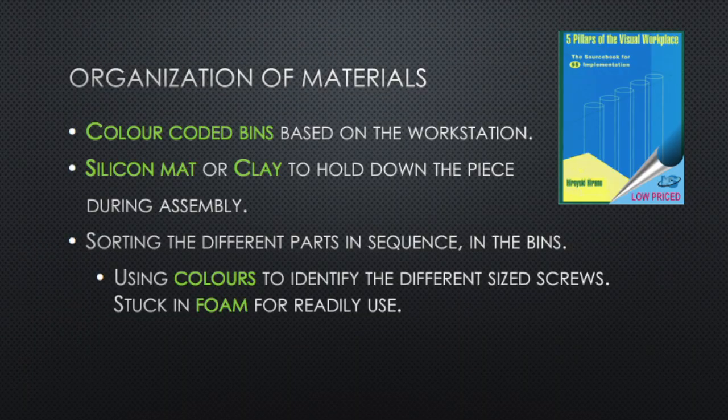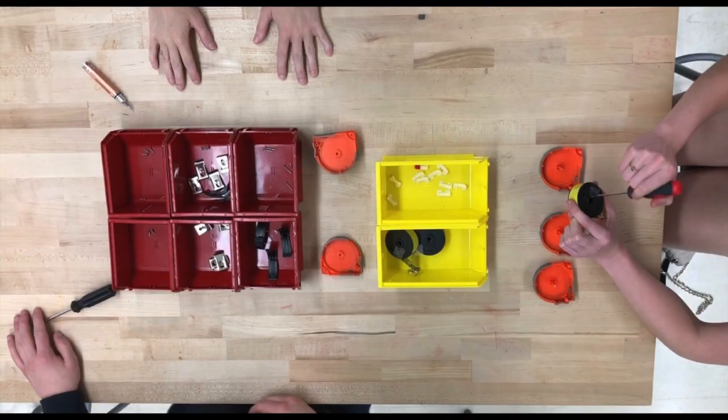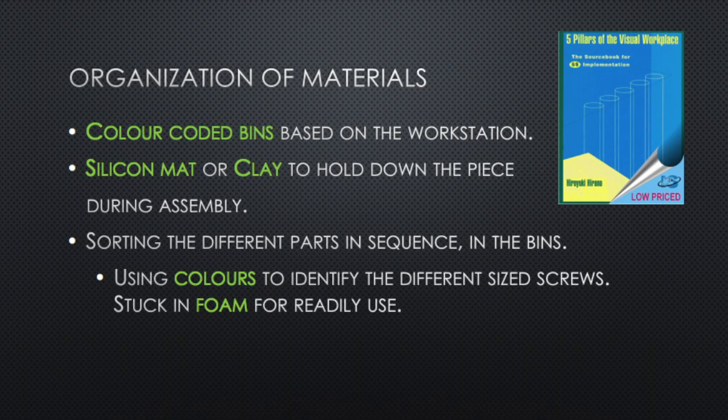The organization of material is important in every manufacturing environment. 5S is a technique used to conduct a high level of workplace simplification. Our team decided to adapt these techniques within our workplace design. All components of the tape measure were separated in different bins based on which workstation they belong to and where they're required in the precedence. This ensures the simplification of the workstations.